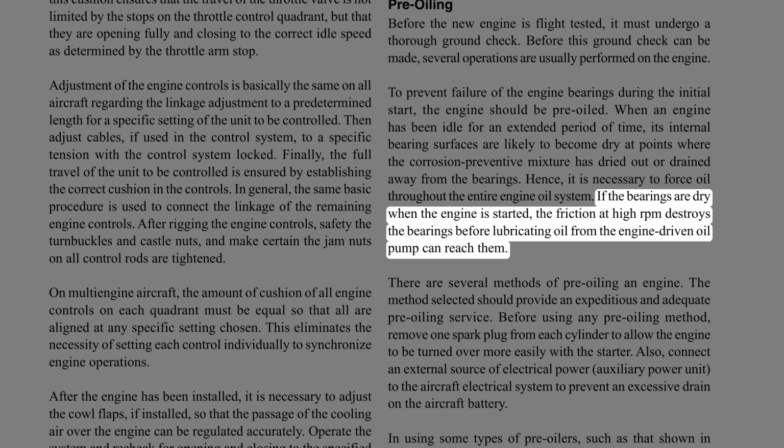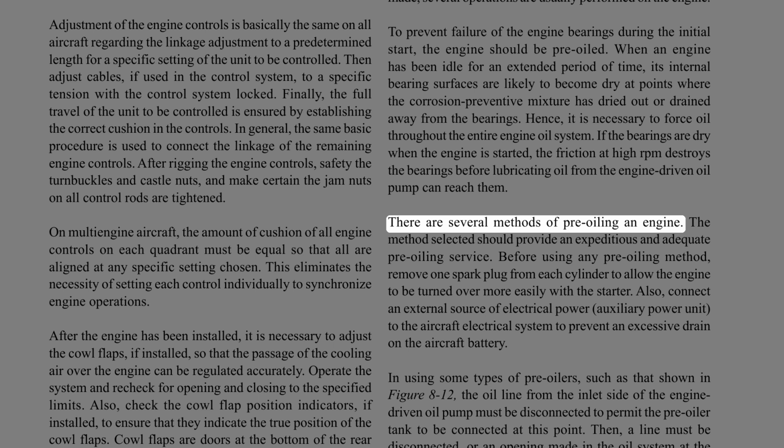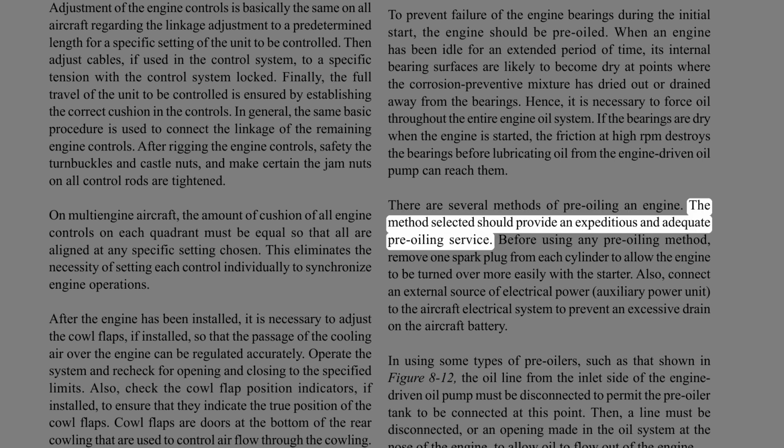If the bearings are dry when the engine is started, the friction at high RPM destroys the bearings before lubricating oil from the engine-driven oil pump can reach them. There are several methods of pre-oiling an engine. The method selected should provide an expeditious and adequate pre-oiling service.